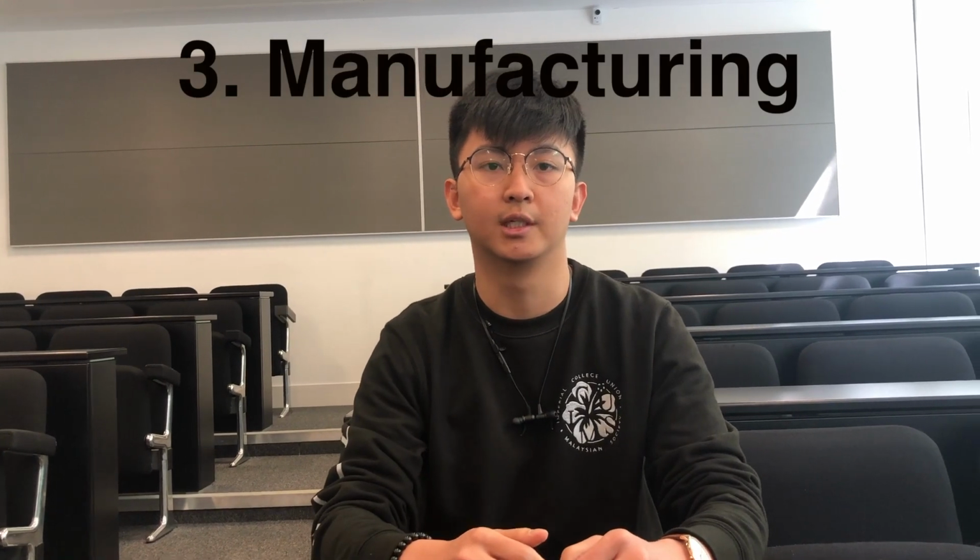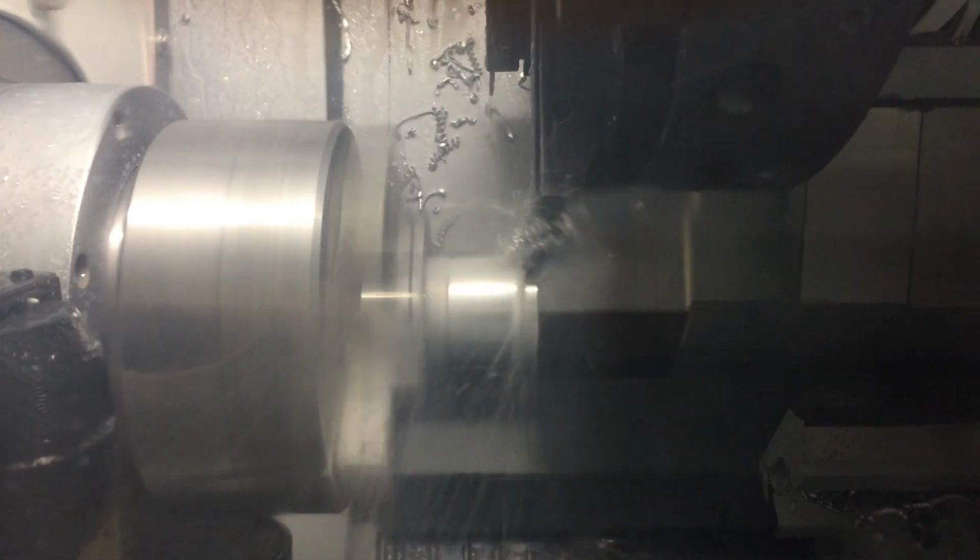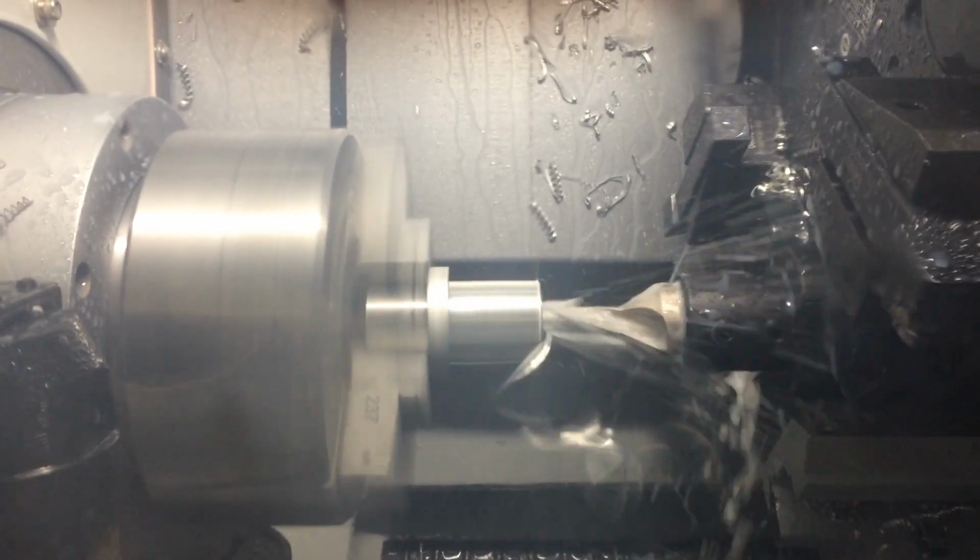The manufacturing was split into two parts: the manufacturing of the aluminium hub and the actual turbine. The hub was manufactured in 4 steps. First, the surface of a cylindrical block of aluminium was smoothed out to achieve the desired diameter using a lathe. A 16 mm diameter hole was then drilled at the center. Next, it was fitted onto a CNC milling machine and the block was cut into the hexagonal shape. And finally, a 3 mm hole was drilled on one of the faces so that it can be secured to the